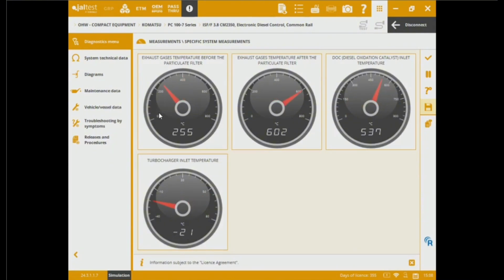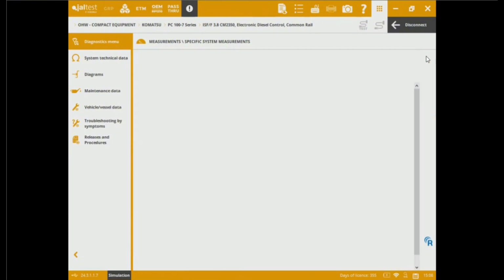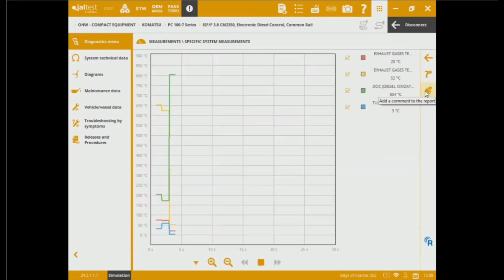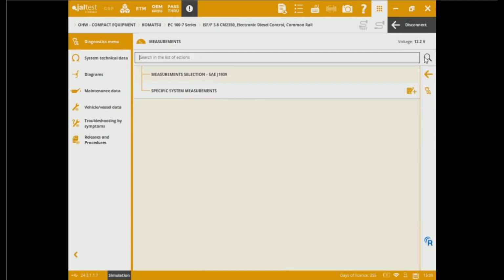We'll have specific measurements within the range specified by the manufacturer, and if we get any wrong readings, we're going to be able to see system alerts right here. A little red bell will appear here and the system will trigger alerts whilst performing wrong measurements, right? I can also even set a time lapse, 3 to 5 minutes, to be able to run an idle test or road test to be able to see if we're graphing these signals in a bad way. So this is a little bit of the measurements and monitoring.